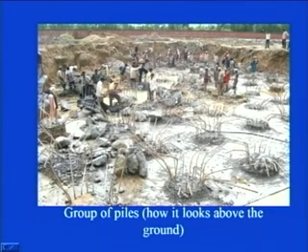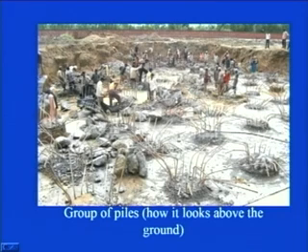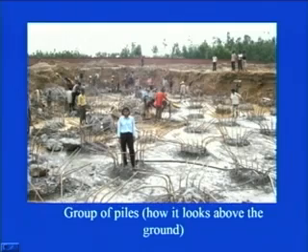Likewise, if you have an area, you design how you have to provide these piles, what should be the spacing, what should be the arrangement, whether they should be arranged in a triangular fashion or rectangular fashion or some other pattern. You first have to decide upon that and only then go for the construction. But this is how the situation looks at any construction site, and this is how it looks above the ground. Then this is another view.